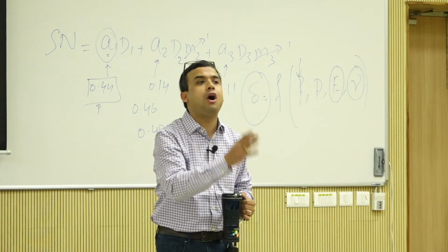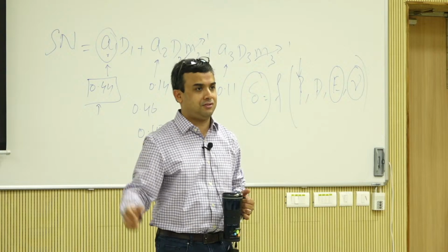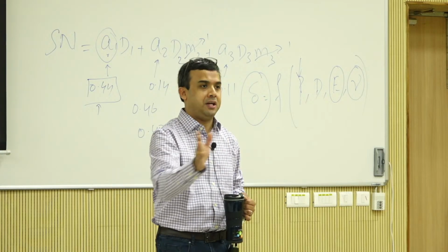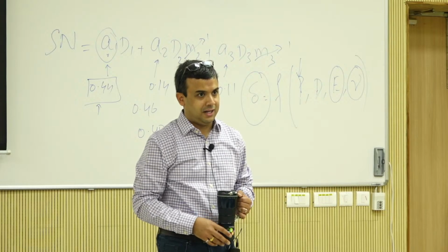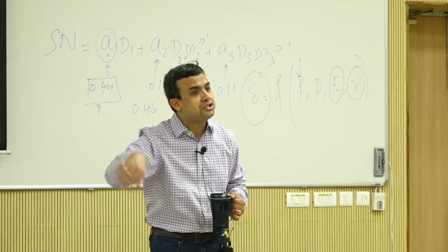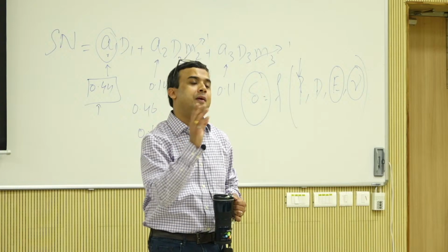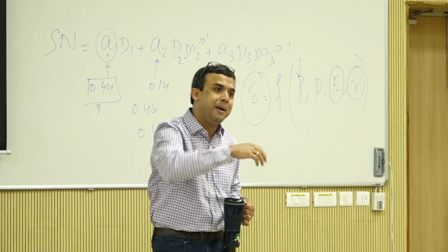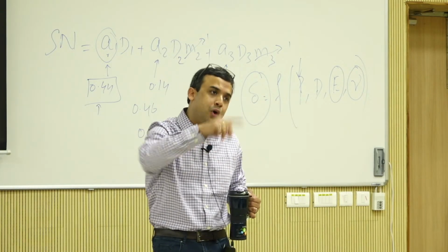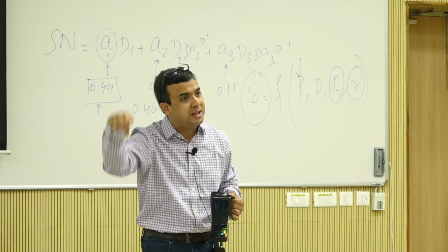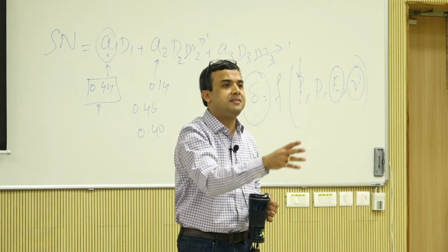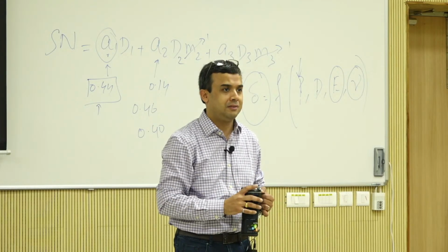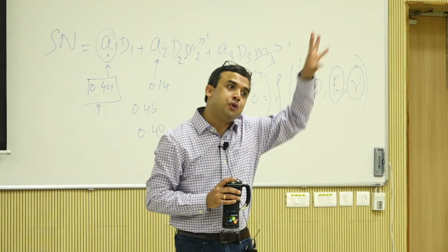You have run all the tests, you have all the properties, but then you go on vacation, right? Now somebody else comes and tests the pavement and says, rather than waiting for Pushpak to come back so that he can give me the value, I'm going to determine, just by measuring the deflections, what properties he established. That's back calculation. The only problem is there is no Pushpak in the real world.